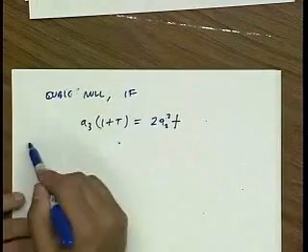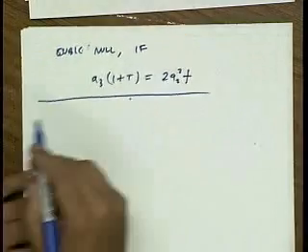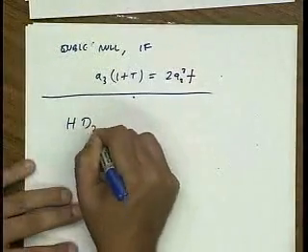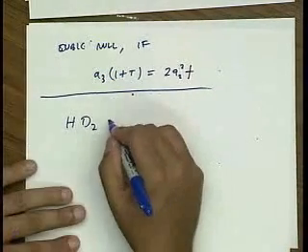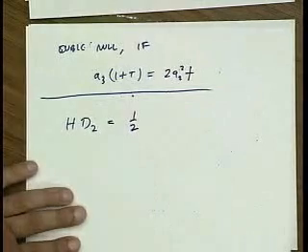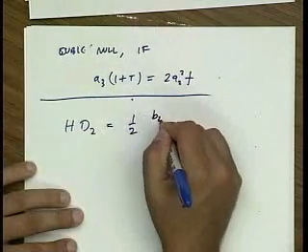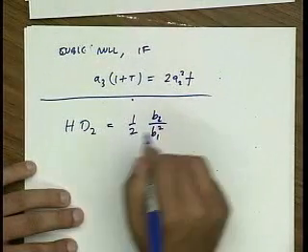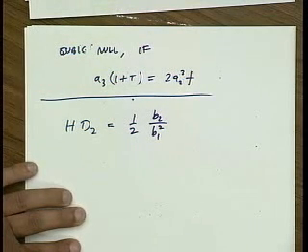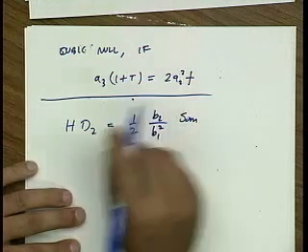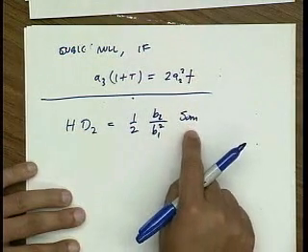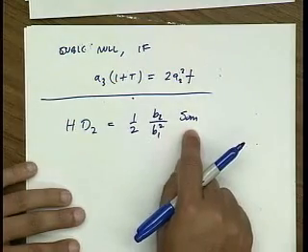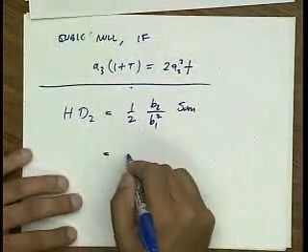All right. So now that we've derived these equations, we can basically go in and plug in the results into all the important metrics. So for instance, if I'm interested in second harmonic distortion, well, the equation I derived a couple of lectures ago is that the second harmonic distortion is related to B2 over B1 squared for a given output signal. It's very important that I compare the same output signal, right? And I'll come back to that in a moment.